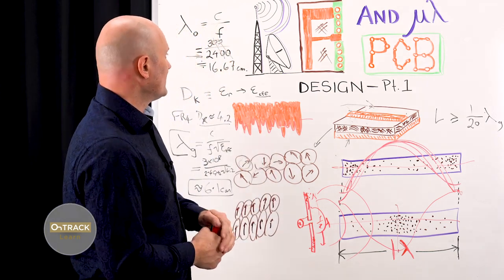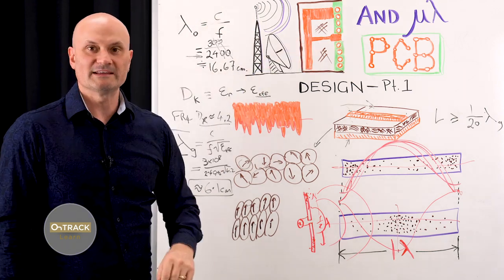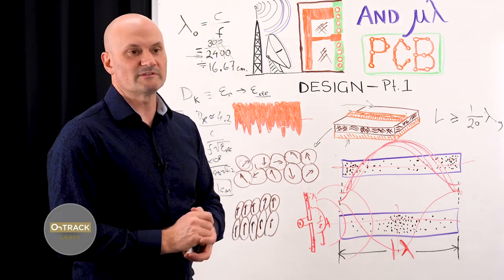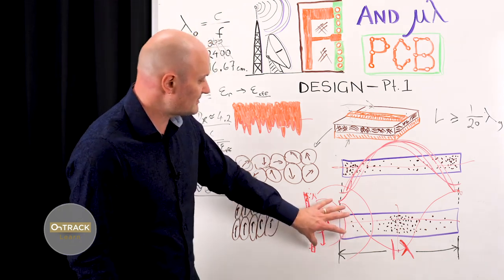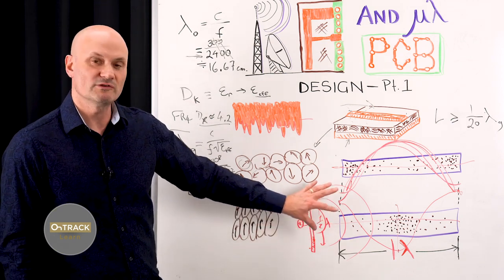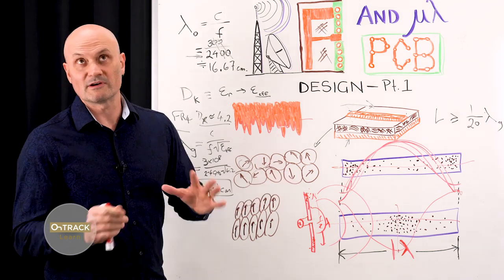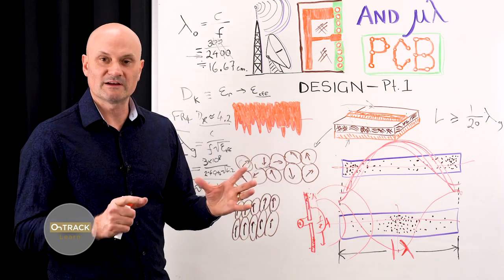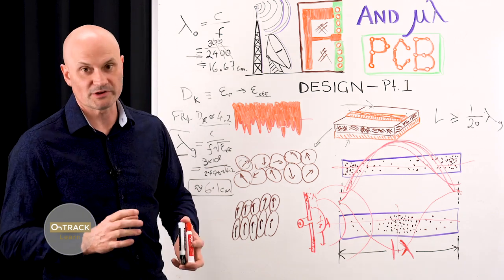And so here I've got RF drawn like antennas, and we'll talk about PCB antennas in our final episode because that's the most complex thing to get to, but we'll give a basic introduction of what kinds of antennas are out there. And also these metal structures that are multiples of a quarter wavelength are very useful in designing the actual board. So we'll go into some detail in episode maybe 3 about what we can do to design an RF circuit using just pieces of copper on the board, which is pretty cool.